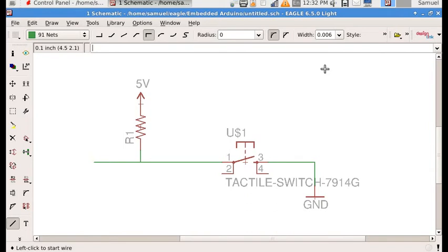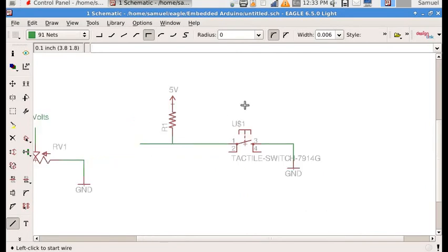Now, one of the things I just want to point out is they tell you that there is either high or low, on, off, 1, 0. There are only 2 states of digital. There's actually a third, well, there's kind of questionably a third state. That third state is called floating, which means it's not connected to either 5 volts or ground. For this circuit to work, we need to be either ground or 5 volts. It cannot be floating, otherwise the microcontroller will have a really hard time with it. So that is basically the pull-up resistor.